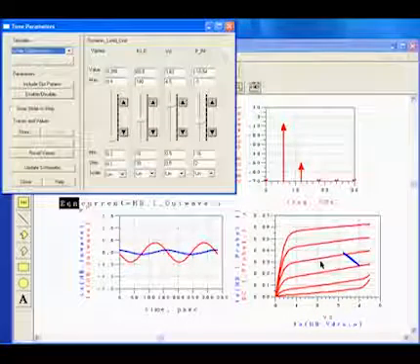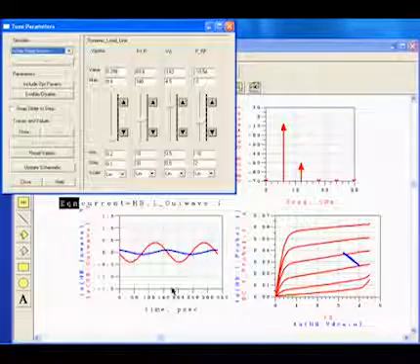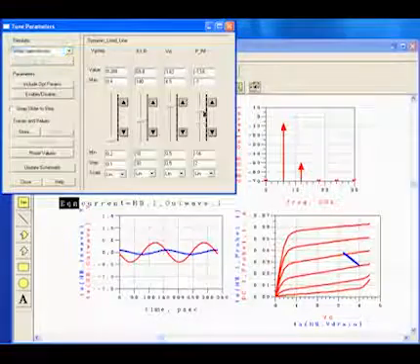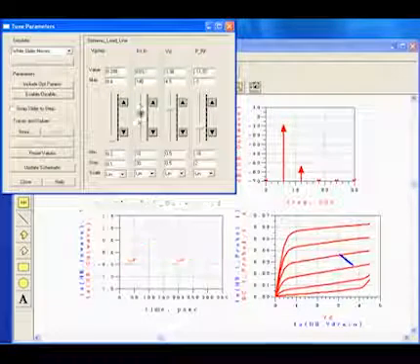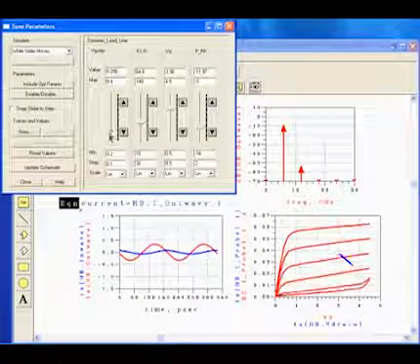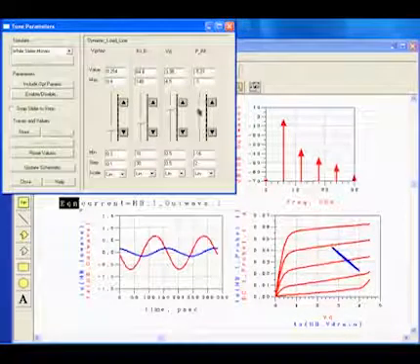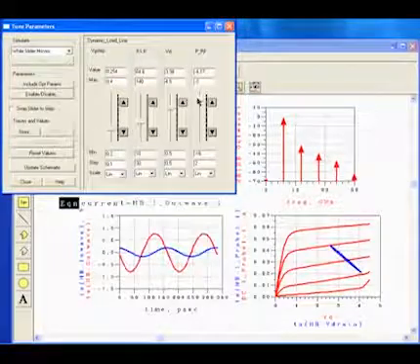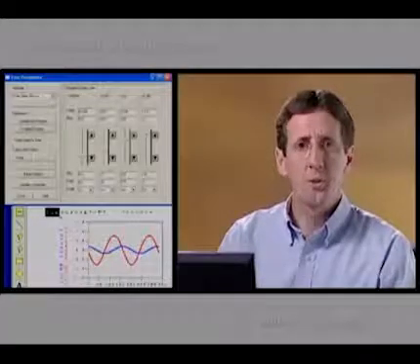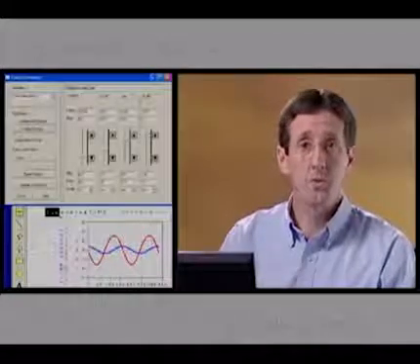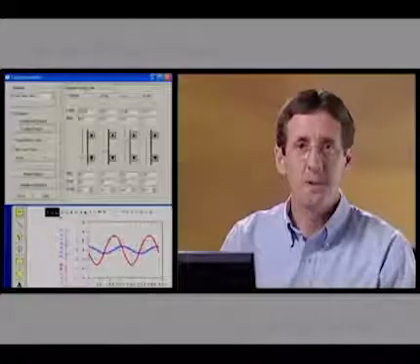What is displayed is the dynamic load line, the spectral content of the output, and the input and output waveforms. You can see the spectral content change with input power, the waveforms clipping, and the changes in the load line as I tune various parameters. We're tuning a complex simulation with a great deal of information being made available, and the results are displayed in real time. I could show you tuning a component in a subcircuit or tuning using a complex modulation signal and showing the resulting eye diagram, but enough about tuning. Hopefully you can see the tuning improvements we've made.